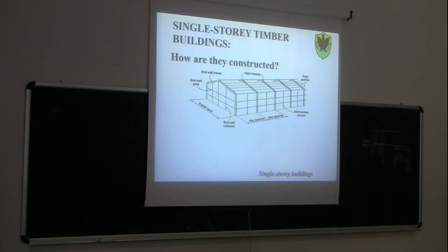Those are needed to support those panels because also if you use sandwich panels made of steel, they are not very big. They are usually quite small. So for this reason, they need to be supported on the four sides. They have to be screwed, yes. So those members here are designed only under horizontal loads. They don't take any gravity load.